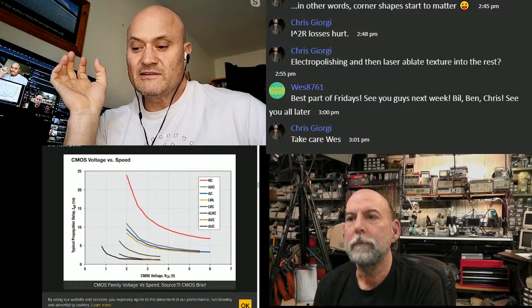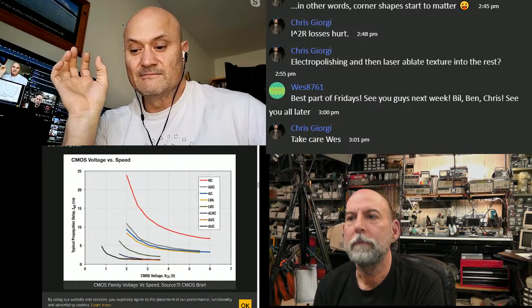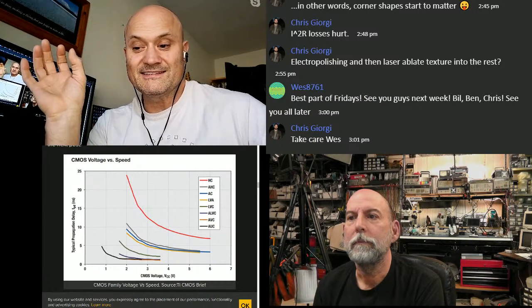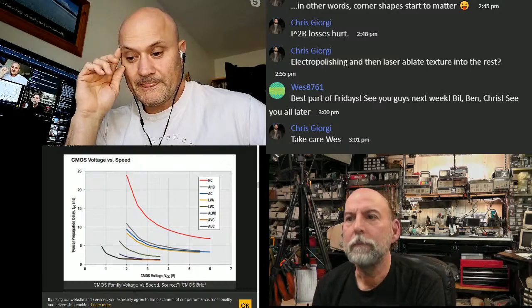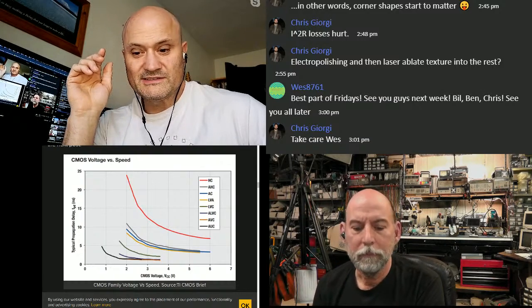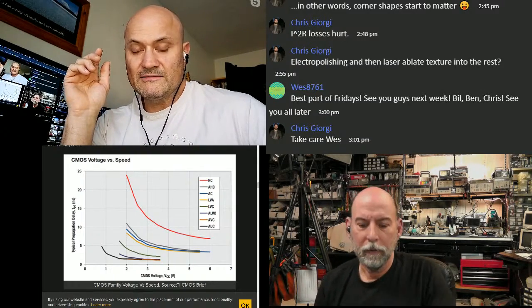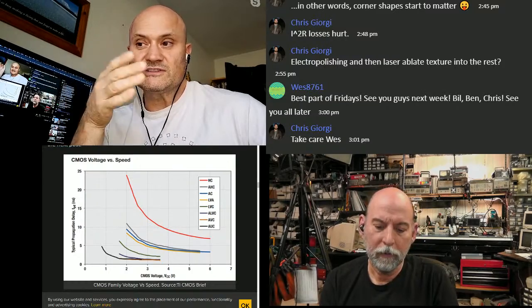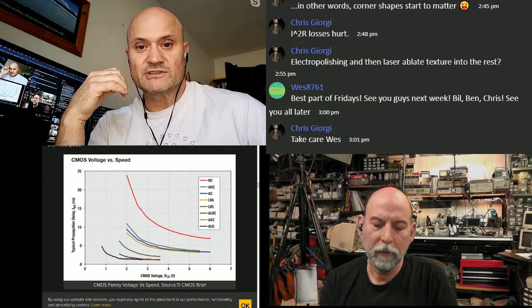So they have specific coupons that are designed in the IPC standards that you can request and pay for, and they'll send you those, and they'll section them as well, so you can look at them under a microscope.